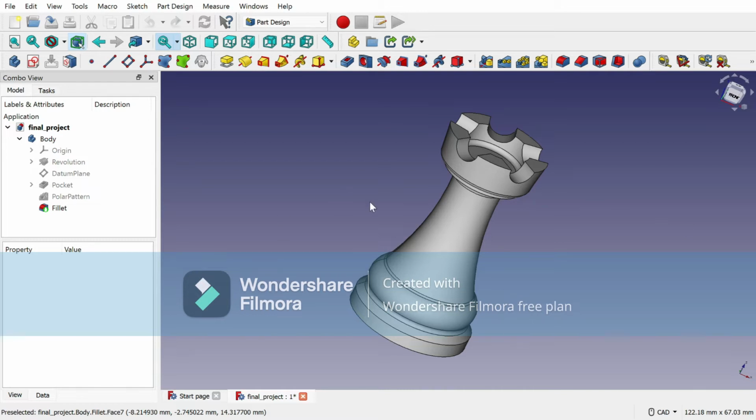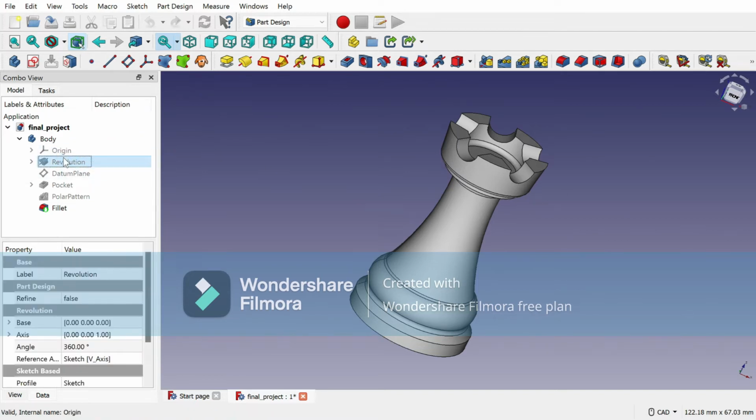So this is what my project looks like once it has been revolved and completed. Now first of all I created the sketch. And then used this option in order to revolve the sketch around the z-axis. Then once the sketch was revolved, the model was more or less complete except for this groove part.